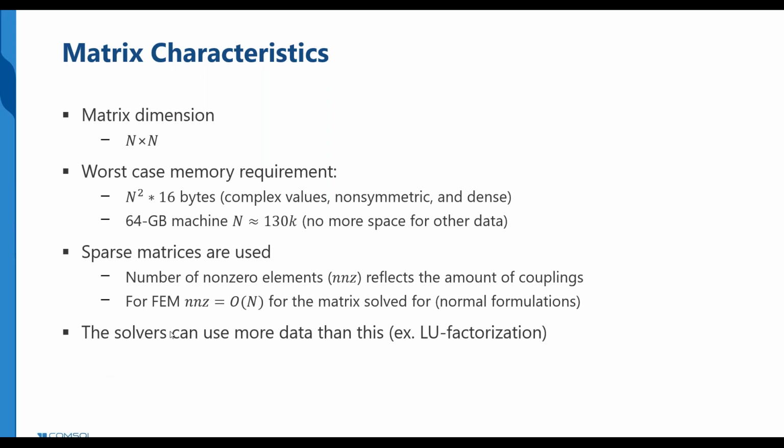On top of that, the solvers and the assembly are using more memory than just the matrix itself. For instance, the direct linear solvers are using LU factorization, and the extra memory needed is called fill-in. It's a fill-in effect. You might remember that from linear algebra in school, that the LU factors can be less sparse than the matrix itself.